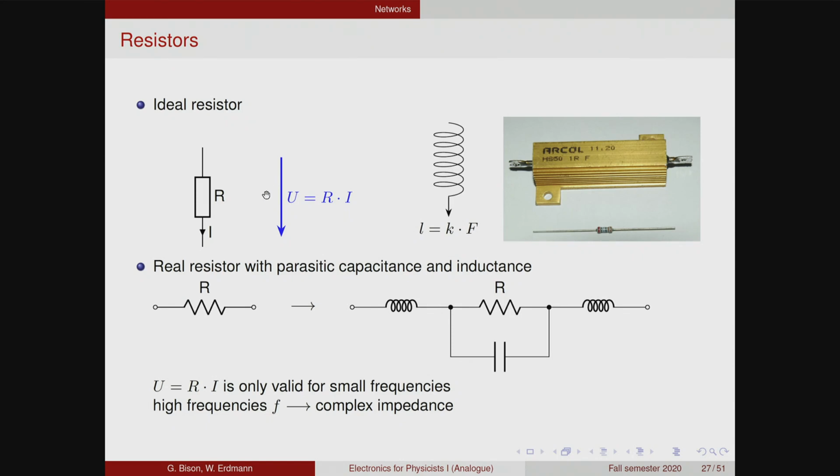Of course, for a resistor, we know Ohm's law applies, and there is a nice correspondence to the law for a spring, where we also have the length proportional to the force. So here we have voltage proportional to current times resistance.